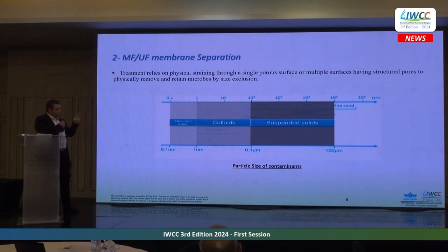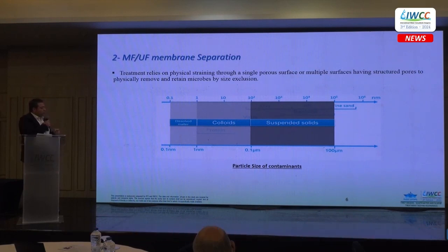Suspended material having the size of 0.1 micrometer to 100 micrometer, while colloidal has a size from 1 nanometer to 0.1 micrometer, and less than 1 nanometer it is considered dissolved. Microfiltration and ultrafiltration practically have nominal pore size from 10 nanometers to about 0.1 micrometer.